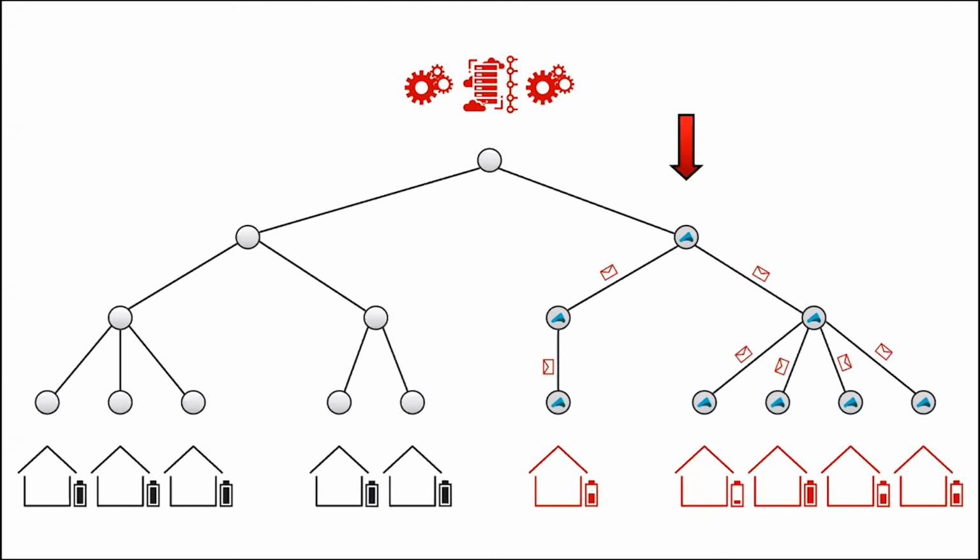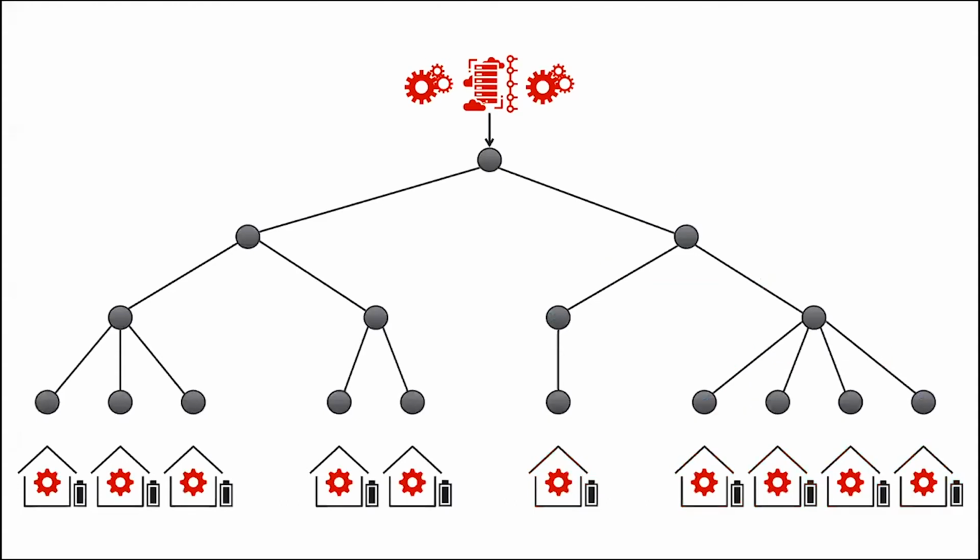The control service then sends a message to each site with a discharge set point and a time frame, and it'll keep retrying until it gets an acknowledgement that the message has been received. Because these logical aggregations of batteries are so large, we stream over these huge collections using Akka streams in these 3 steps. So resolve the sites, read all of the telemetry, and then send all the control set points. And this actually runs in a closed loop every few minutes.